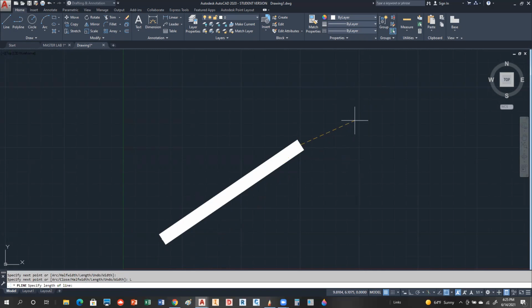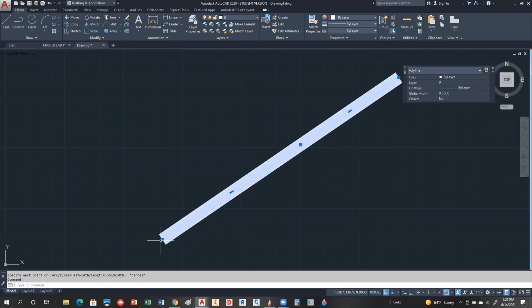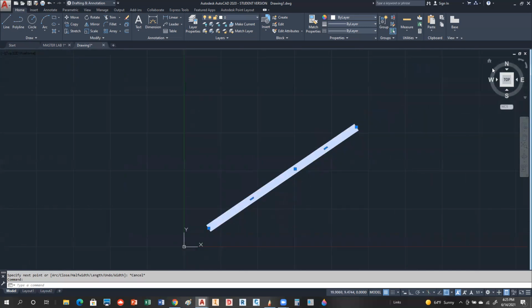Now, if you specify a positive length, it'll push it out this way. And if you specify a negative length, it kind of puts it on top of itself. So if I said, let's say 5 units, notice it shot it out 5 units. And here's the other thing that it did. It didn't just extend that line out. What it did was it actually attached another segment. So you'll notice if I click on my polyline, there's the vertex, the second vertex, and the third vertex. So I actually have 2 line segments, one right there and one right there. Turn that guy off so he doesn't keep popping up on us. All right, so that's what we would call the length option.